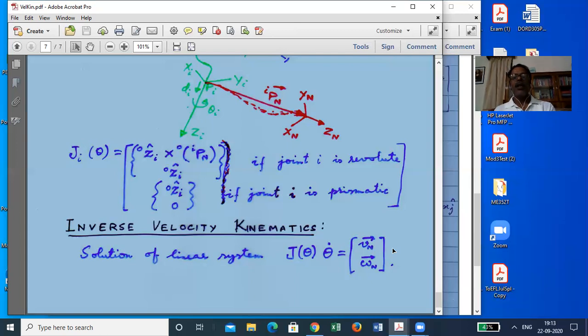and matching the situation in the algebraic sense with the real picture that takes place for the manipulator physically. So before that we will study static force transformation, because the velocity motion mapping and the static force mapping have some very interesting similarities, and rather than similarities they have a reciprocity. Whatever happens this way for velocities, it happens that way for forces. So that we will see in the next lecture. So here we stop for this lecture.